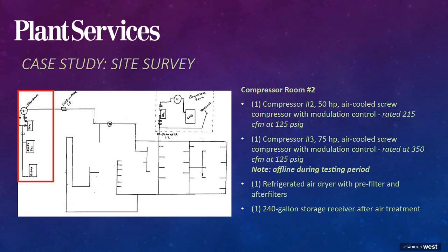In addition, there are multiple compressor rooms like this. When you have it, like we've shown here, you want to ask why. Was it because a compressor came with a specific piece of equipment? Was it because one particular area of the plant couldn't maintain the necessary plant pressure? Generally, a fresh perspective can unlock long-forgotten history on your compressed air system and help improve system efficiency along the way.